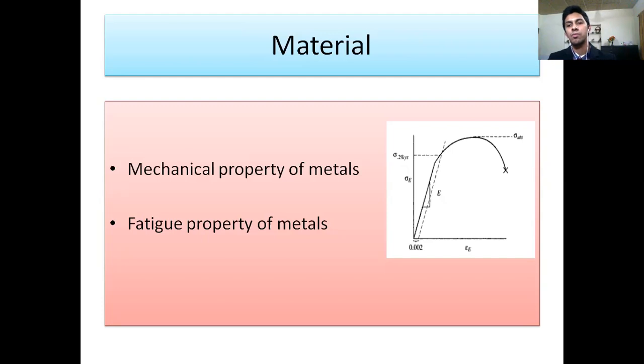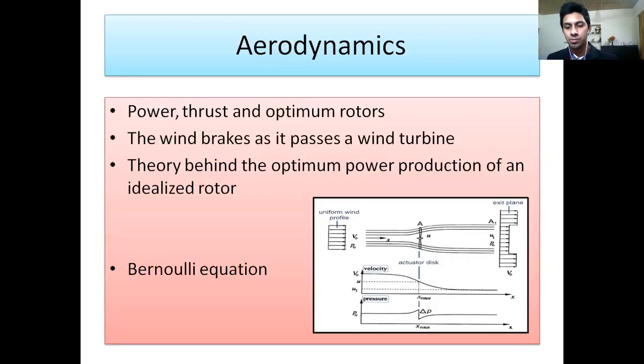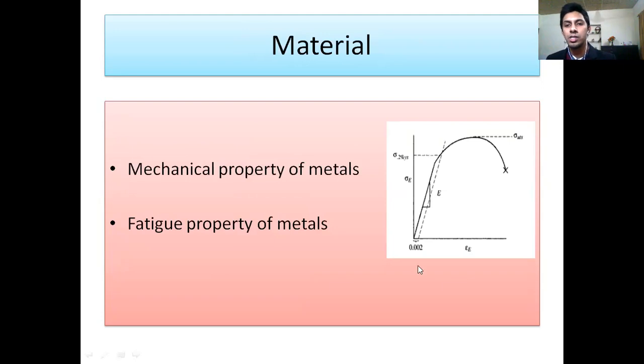And here is a curve of the stress and strain. Here is the yield stress, and this is the plastic deformation point. The linear relationship between stress and strain is known as Hooke's law, where E is the modulus of elasticity, corresponding to the stiffness of the material. So the stiffness is basically the slope of this line here. The stiffness is related to how strong the atomic bonds are, and this is also related to the melting point.